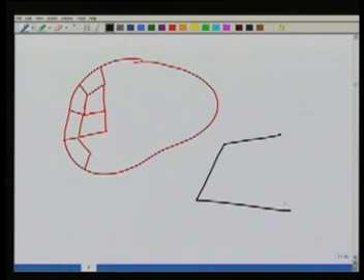Okay. So when I have a mesh of quadrilaterals, what do we do? Then we do not have this luxury of having these two perpendicular edges for which we define these individual functions and take the product. I cannot do anything at the physical level, that is at the level of the physical element. So for that, I'll have to map this. What we do is we map this physical element to a master element. So we'll have to define the master element now for these quadrilaterals. Okay, and we define the master element in such a way that I can use this tensor product representation to get my shape functions in the master element.